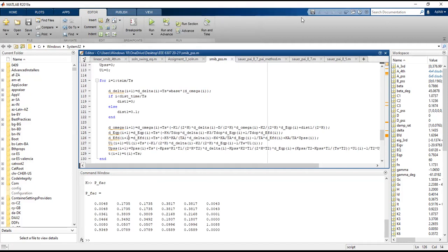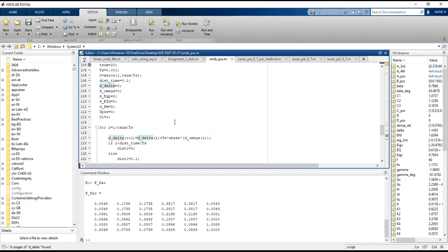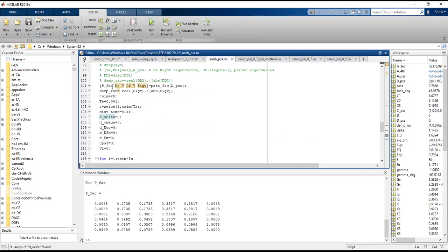No question. Okay, then. So what we have done today, we have designed PSS with the steps that we discussed. And we have seen the application of participation factor in identifying the participation of eigenvalues in different states, or vice versa, whatever you say. I mean, they are linked, how much any states and any eigenvalue are participating in each other. In other words, they are also called modes. Sometimes you will find this term modes. So these eigenvalues are also known as modes.